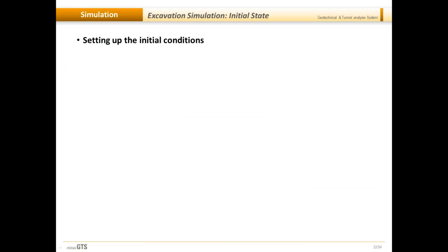So setting up of initial conditions is very crucial. What happens is, if we know what the history of the soil strata has been, then we should model it accurately. If we know what stress paths or stresses or prescribed displacement has already gone through the soil strata, then we should apply that onto the model in the very first stage.